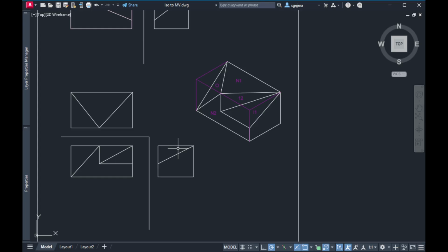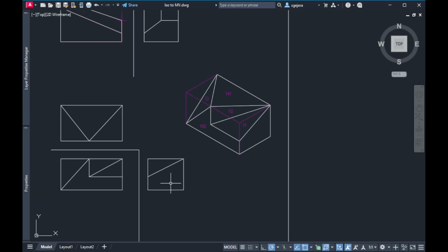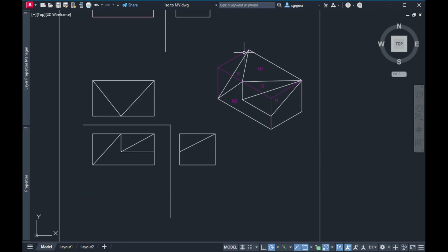And the way we determine it is through the use of a hidden line. Okay? So, if you try to do yung correct visibility rule natin, it will still apply, no? Parang mangyayari pa rin is you will still arrive at the same conclusion na mangyayari is that line will be hidden because of if you try to create the projection lines. Pero without even creating projection lines, kayang-kaya natin ano to, no? Just by observing, kasi ito nasa likod to or nasa left side kasi siya. So which is technically the back side when you're looking at it from the right side view, no?